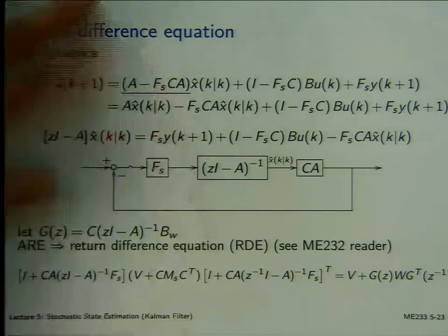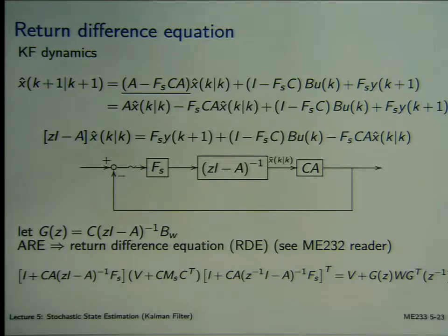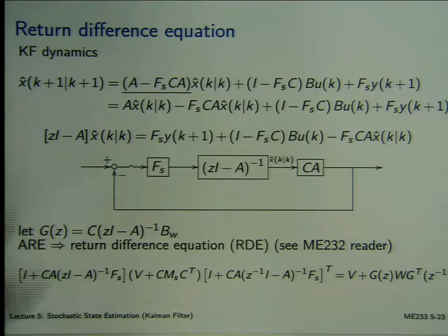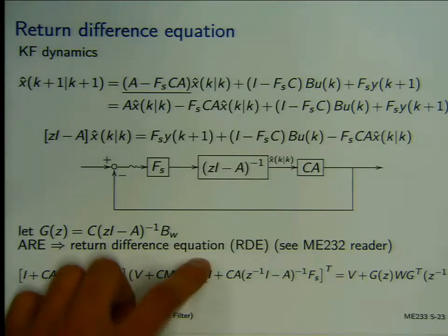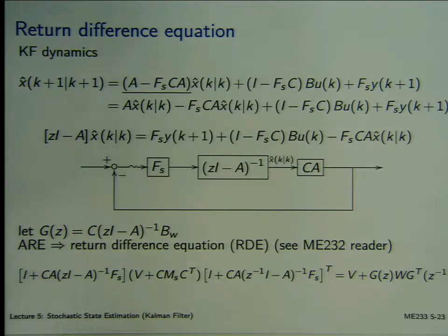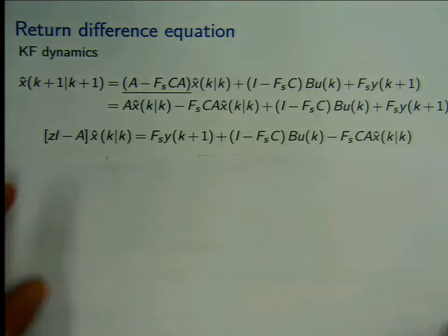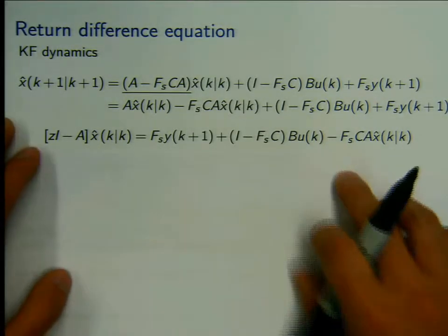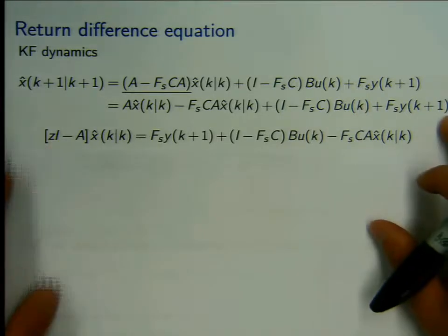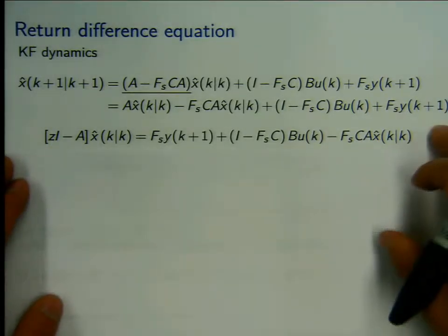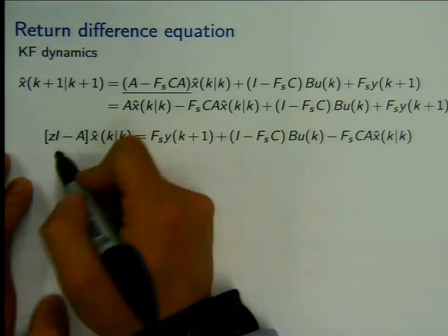So in the Kalman filter, it turns out the analysis is quite similar. There's also a return difference equality in Kalman filter, and there's also a symmetric root locus in Kalman filter. So, as I said, it's going to be a little bit involved, and maybe a little bit dry, so stay with me on this.